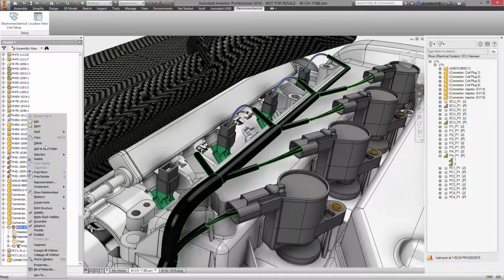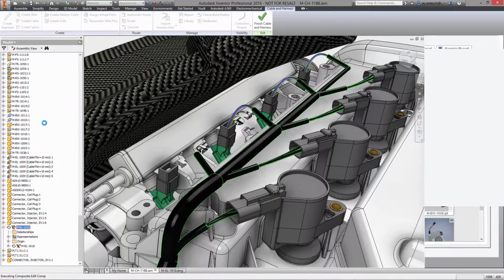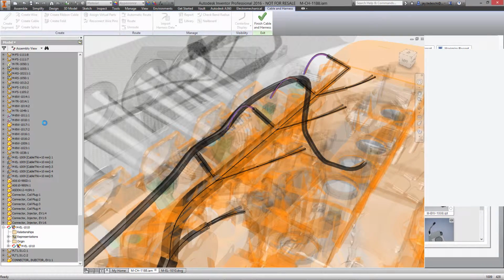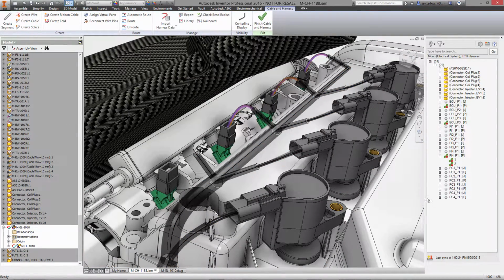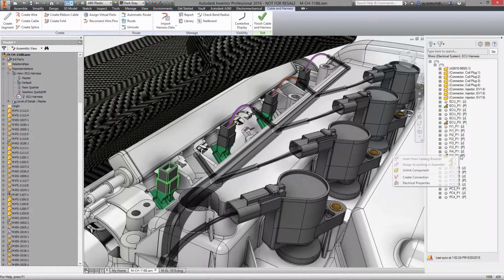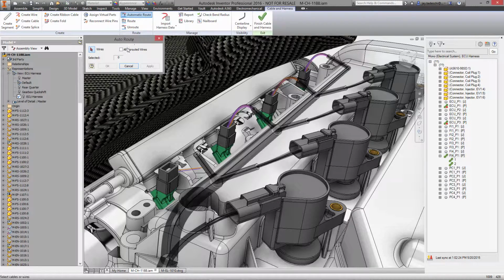So let's go ahead and activate the wire harness itself. Okay, see pins, they're the wires. There's our fuel injector plug, and wire 1 and 2 are not currently attached, so we'll select create connection. And there, you can see it right there now. The violet and orange wire are automatically attached to the pins.